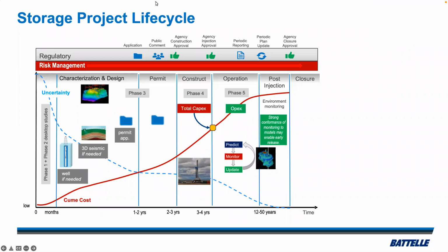So there are a variety of carbon capture technologies. I would say the most popular is amine. You're basically building a chemical plant and you're using a chemical to grab the molecule of CO2, and you use energy to heat and cool. That allows at one temperature for the molecule to be grabbed and at another temperature for it to be released.